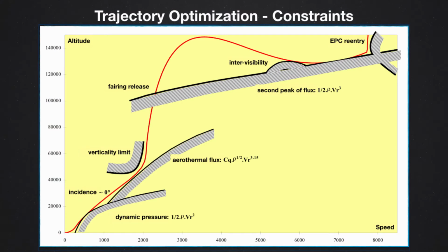On the lower part of the slides, you can see actually the ground track of the Ariane 5 launch to the east, so to GTO orbit. So the launch pad is Kourou, and then you have the Natal ground station, the Ascension ground station, which is a little island in the middle of the Atlantic Ocean. You have Libreville, which is in Gabon, and you have Malindi in Kenya, okay? And these 5 stations, with their own mask, so with their own visibility field, are able to track Ariane 5 from launch to insertion in GTO orbit, okay?